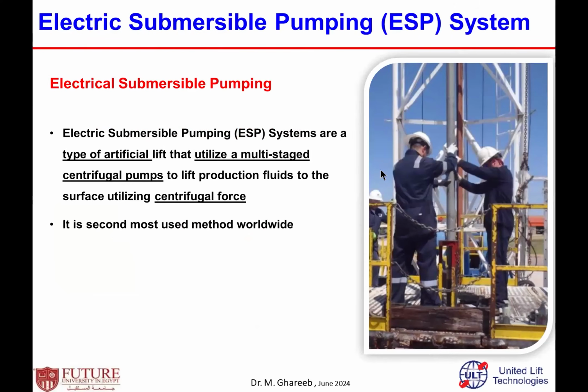Then what is artificial lift? What is an electric submersible pump? An electric submersible pump is a typical artificial lift system. As I said, it's a dynamic displacement pump. It uses multi-stage centrifugal pumps to produce formation fluids, whether water, oil with gas, two-phase flow, and so on. Mainly it's using centrifugal force to give dynamic energy to the fluid.